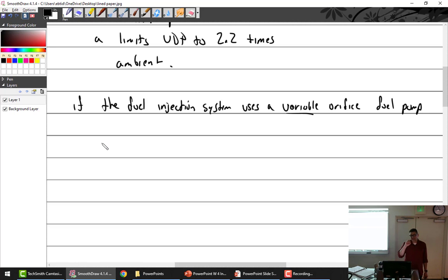As I add throttle, air comes rushing in, the engine speeds up, but the turbo is lagging, so I don't have a good solid amount of manifold pressure. It's more ambient. I've got to wait for everything to spool up, so I have to wait a second to give it the fuel to match what it's going to have.